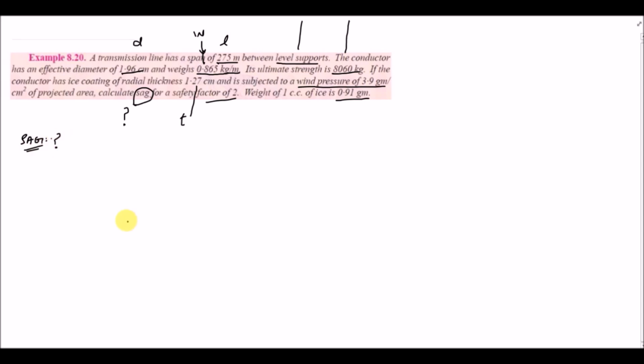Right? We know the formula of the sag is WT L square over 8T. So now I'm not using the weight of the conductor, I'm using the total weight, which also includes the weight introduced by the wind pressure and also by the ice loading, right? So this is WT, then we have to calculate the tension, but we know the span. I will say this is equation A. So starting from the tension, we know the formula.